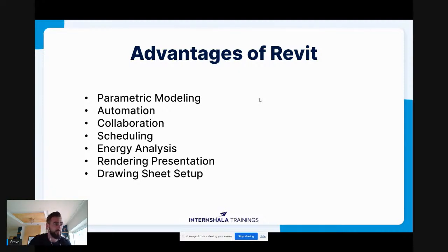We'll move on to collaboration. One of the more distinct differences between Revit and AutoCAD is the ability to allow multiple users to work in the same Revit model at the same time. Where one user can make changes to a DWG file at a time within AutoCAD, within Revit, we can have multiple users work on the same file. By using the Sync with Central tool in Revit, users can push their model changes to a central model while also pulling any changes from that same central model made by their colleagues into their local copy of the model.